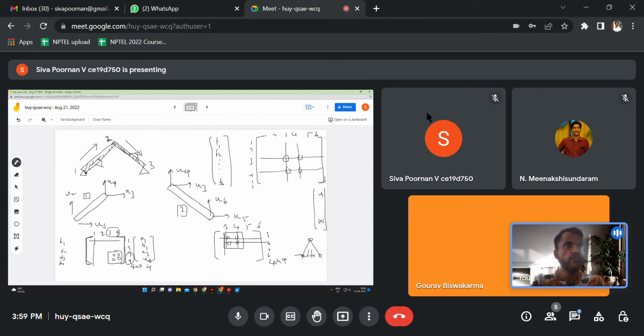Okay, so arresting this basically means that we are arresting u1, u2 and u5, u6, right? So basically we'll have u1, u2, u5, u6 to be 0, and only u3 and u4 to be non-zero. So these things will become 0, and you have non-zero values only at these 2 points, right? And what about forces? What happens to forces? Yes, you have F3 and F4.